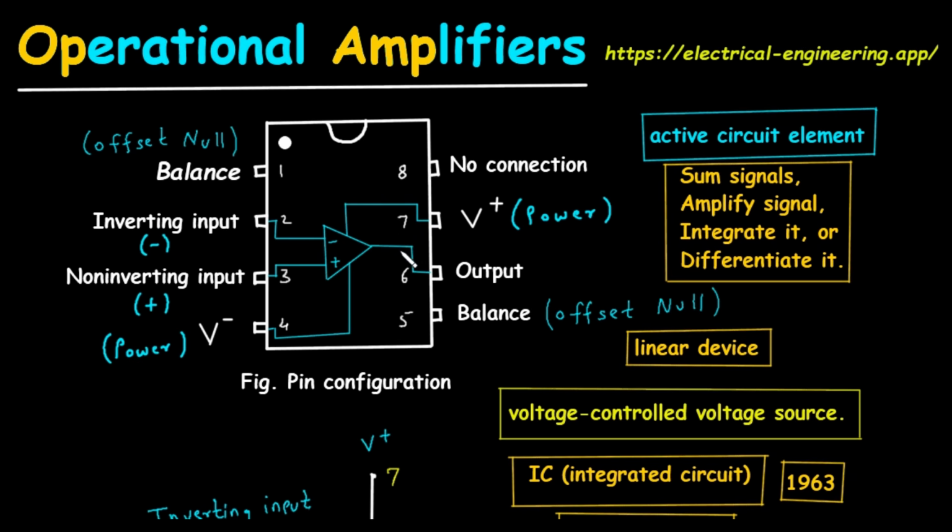Ideally, if both inputs are at the same voltage, the output should be 0. In reality, there might be a small offset voltage. These pins allow you to connect a potentiometer to null or zero out that offset. For most basic applications, these are often left unconnected. So generally, for a basic application, we can keep this unconnected.